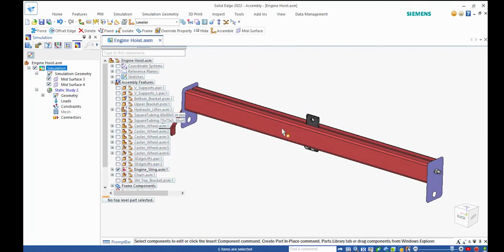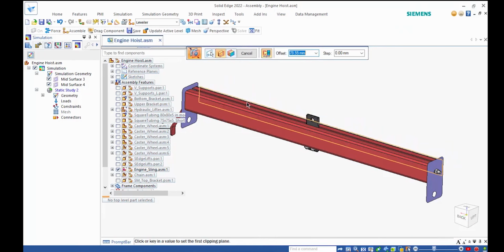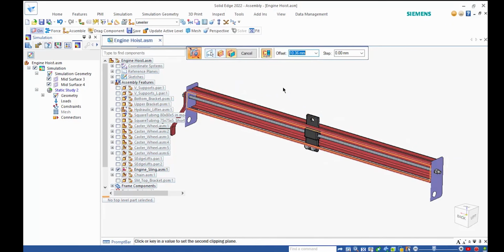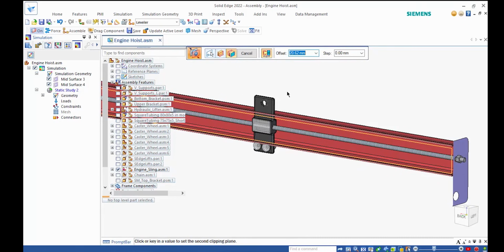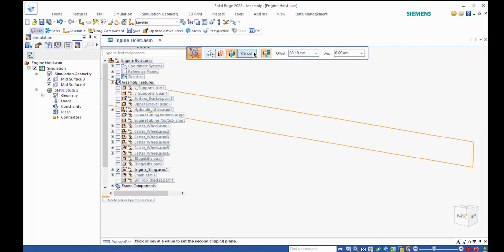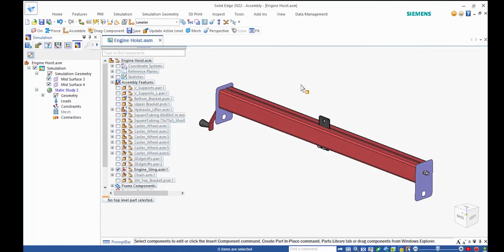Let me explain a little bit what's happening here. If I section this assembly, you can see that inside we have this threaded rod, and this threaded rod can bend because of its length. If we exceed a certain load, it will start bending significantly, and that will prevent the centerpiece, which is supposed to move along that threaded rod. So we need to prevent that. In order to do that, we need to make sure that a certain displacement of that rod is controlled very tightly. So let's go and do that. So we have the geometry.